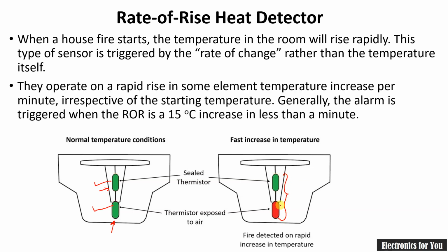Generally this detector triggers if the temperature rises by more than 15 degrees centigrade per minute. So say in 1 minute the temperature has risen from 30 degrees to 45 degrees or more. In such a case it will give the alarm. That is the rate of rise heat detector.